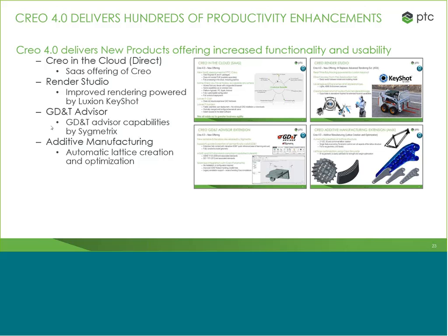We're going to get to additive manufacturing later on in the deck, but what are we doing there for usability, functionality, and productivity? We're going to allow you to automatically create this complex lattice structure. Not only can you create it, but then you can go ahead and simulate it and optimize it based on what are the constraints, what are the limitations, how do I make this as strong as possible, yet maybe think about how do I make it as light as possible as well.